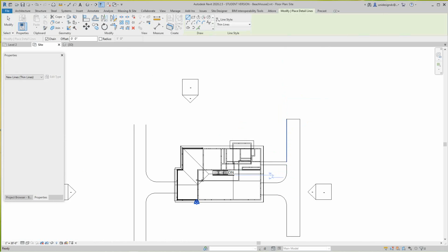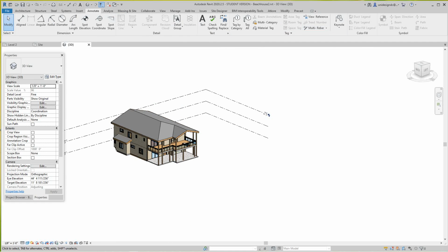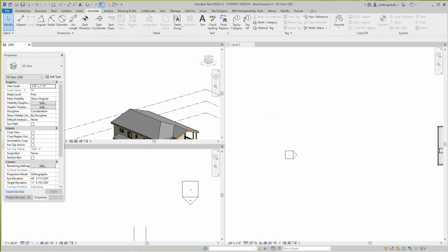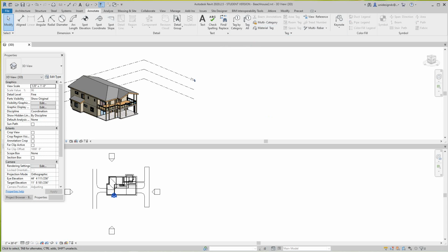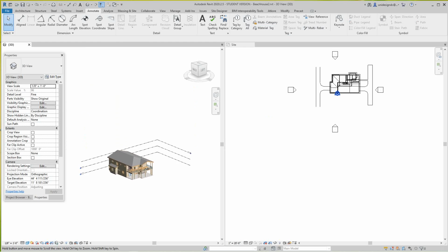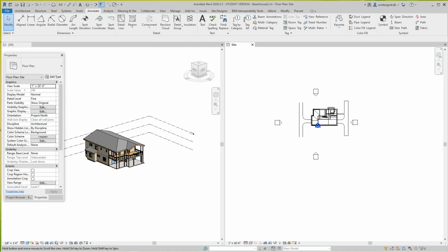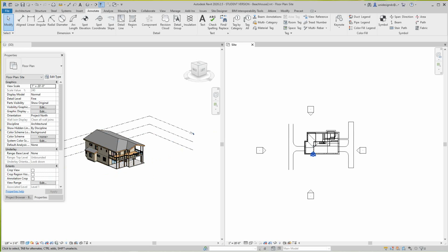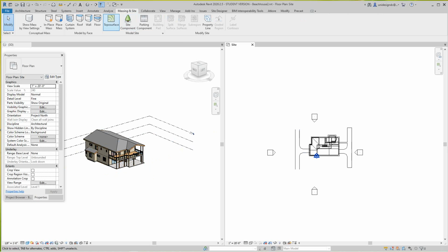So right now, I'm going to go to my 3D view. Actually, I'm going to tile these views. I'm going to do zoom all. I don't really need to see this guy, he can go away. So I'm going to tile these again. Now we're in our site plan over here. And what I'm going to do now is what we call a topo surface.